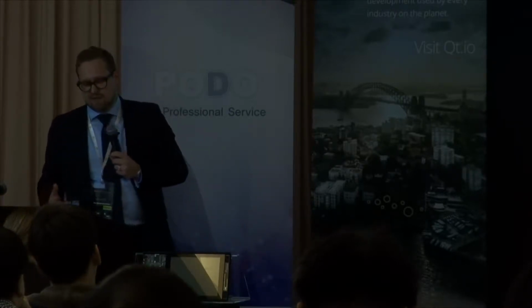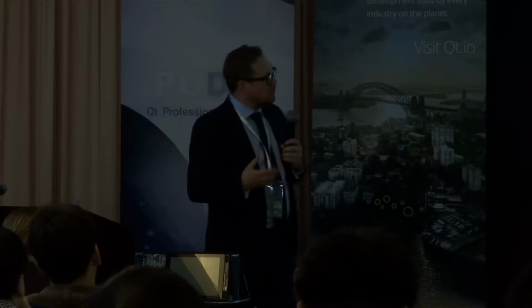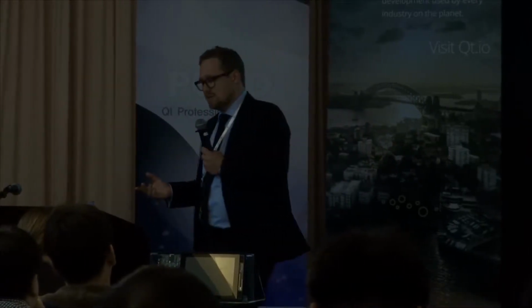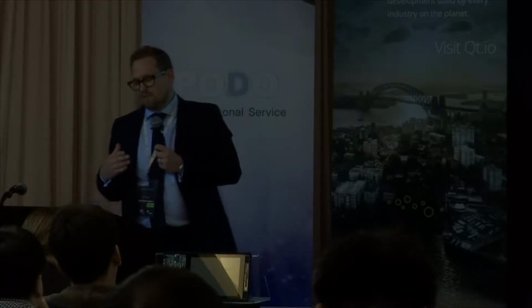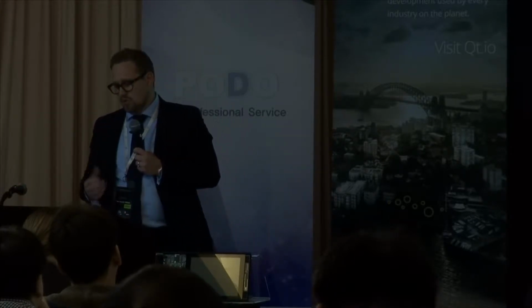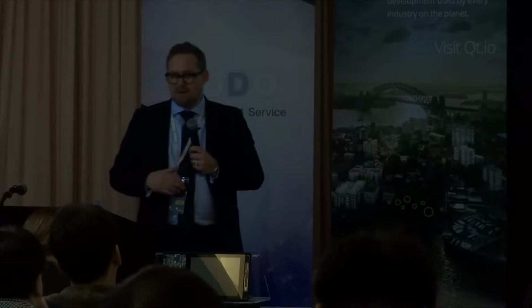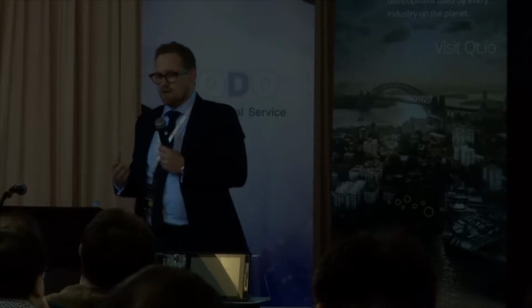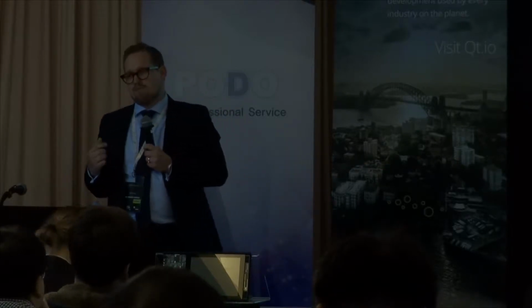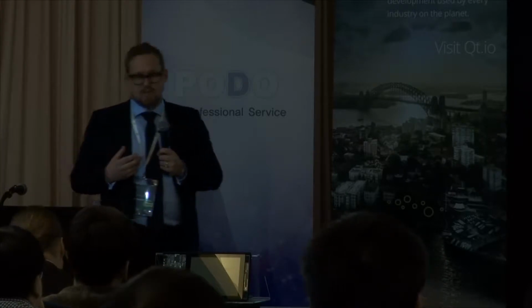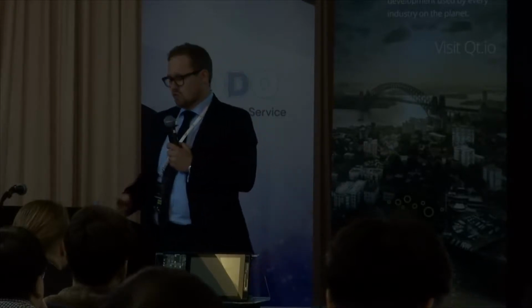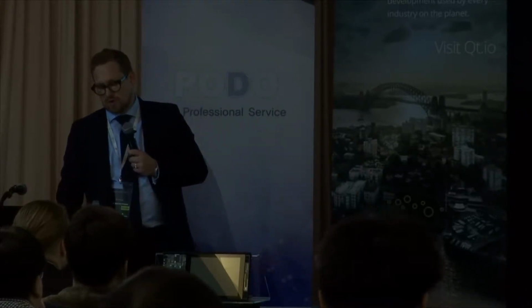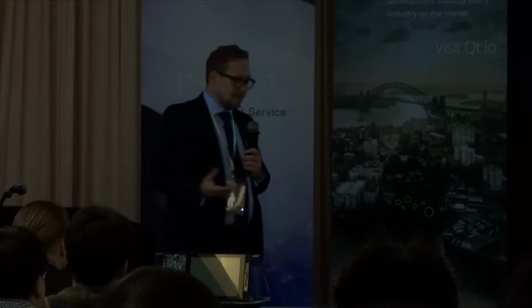So that's easy to do if you want to have a small embedded device that doesn't cost too much. And what you want to be looking for there is the Android Open Source Project, which is a basis. And then most hardware vendors will either just give you their own SDK and NDK, which is from Google or directly from them. But you really want to have access to their source code and their changes and patches to the AOSP, the Android Open Source Project, so that you can build your own SDK and control the tools and the workflow you're working with there.